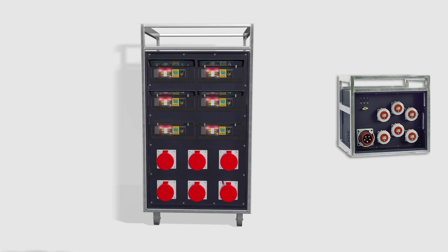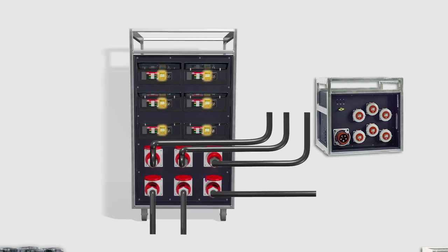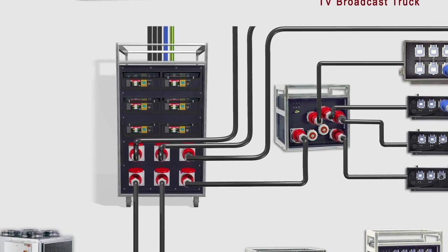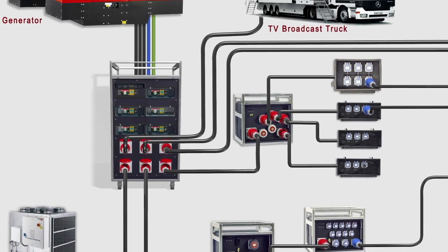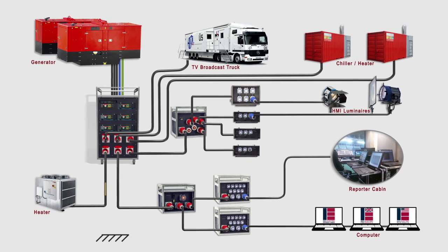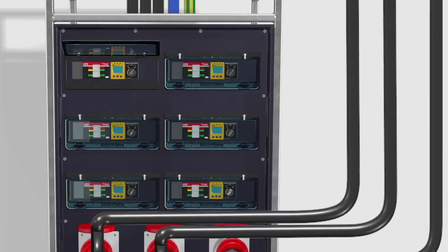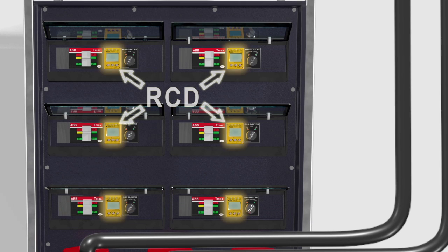As well as being protected with fuses or circuit breakers, electrical systems are commonly fitted with residual current devices, or RCDs. Fuses and circuit breakers serve mainly to protect leads and cables from overload caused by short circuits and ground faults. Residual current devices, on the other hand, protect people from electric shock when they come directly or indirectly in contact with a live conductor.